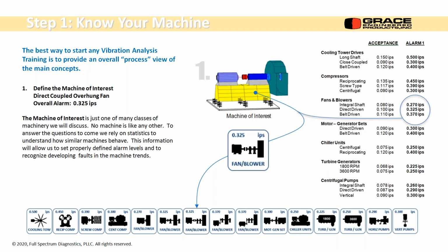Okay, next one from Dennis. Motors seldom run right at rated RPM. Shouldn't all your frequency measurements be based on actual rotating speed versus rated? Yes. The rated speed is on the nameplate, and it might be a few RPM off. It depends on what the final load is on the bearing or on the machine, the motor, what have you. You should always use the actual RPM versus the rated RPM. If you're looking in a spectrum, you put your cursor close to what the rated is, and you will get the actual.